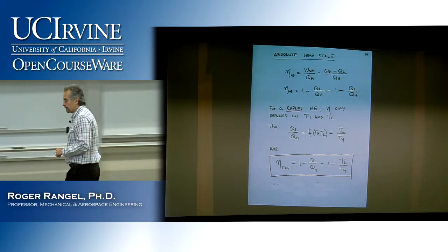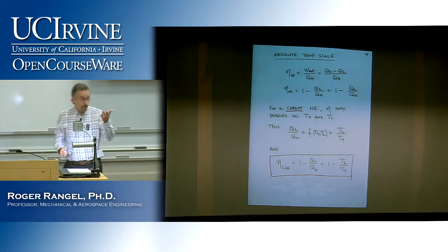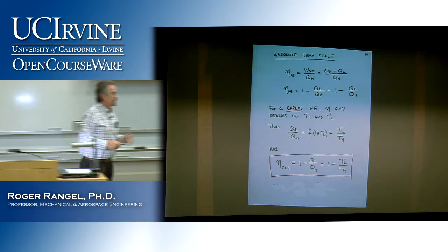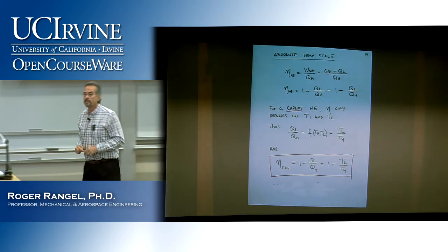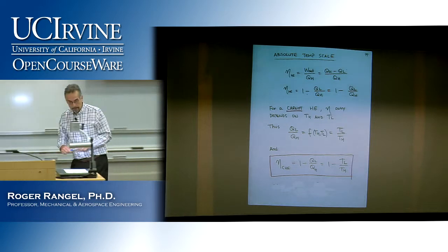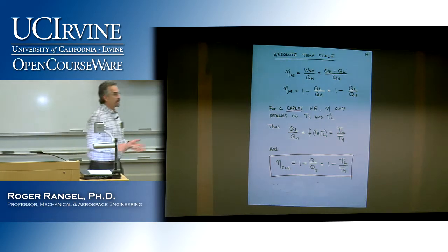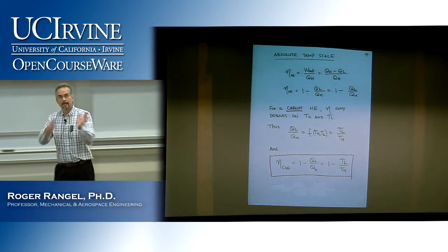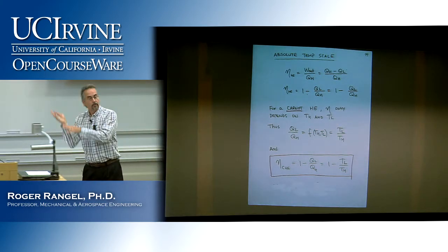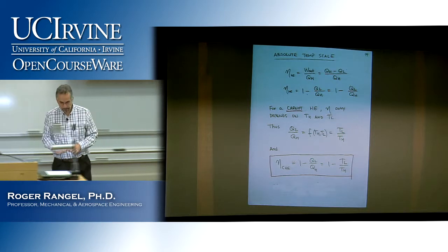It says that's impossible. The easiest way to think about that is that the Kelvin-Planck statement is telling us that Q sub L cannot be zero. There will always be a Q sub L, which is why, of course, the efficiency is always less than 100%. You cannot make all of the heat input into work available to you.